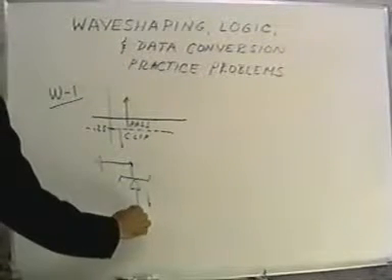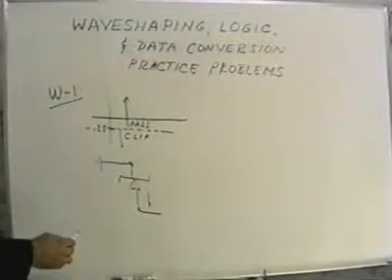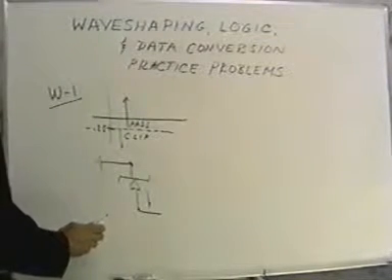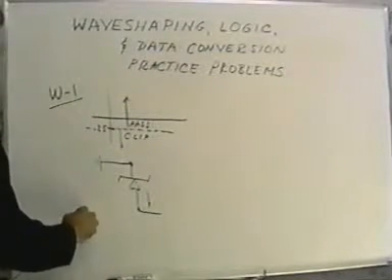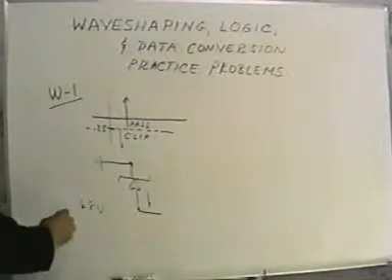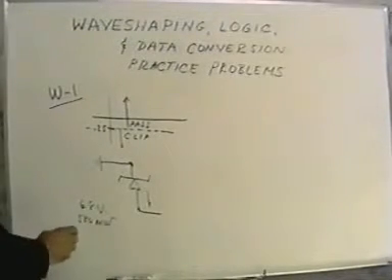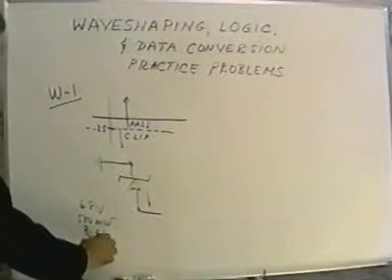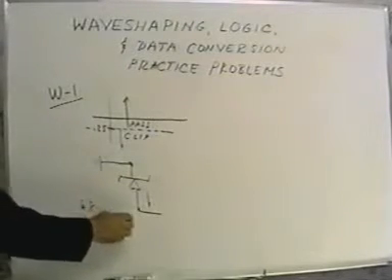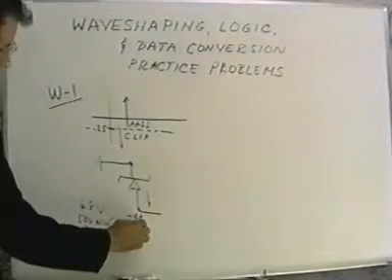And what we'd like to do is to pick a Zener diode, and at random, a good choice seems to be from what's available in the table, to use one that is a 6.8 volt Zener diode. It's just an arbitrary choice, 500 milliwatts, and has a Z sub S equal to 5 ohms. That's a good choice.